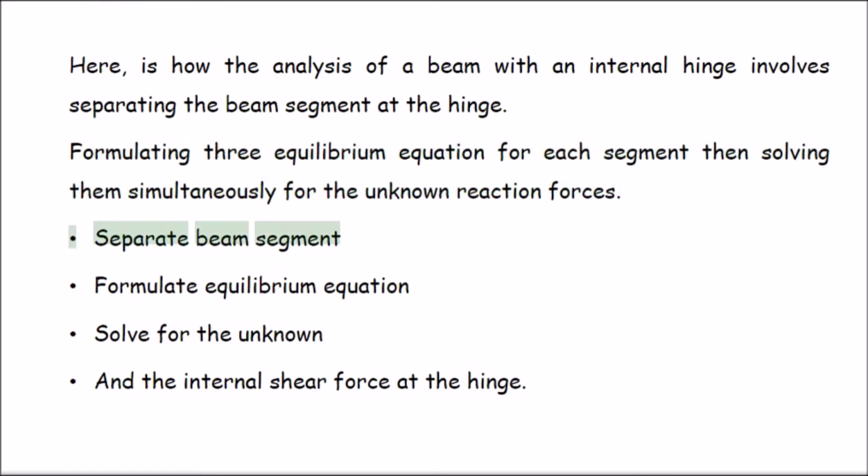Separate beam segment. Formulate equilibrium equation. Solve for the unknown reactions and the internal shear force at the hinge. Free body diagram of the beam. Here is the free body diagram of each beam segment.